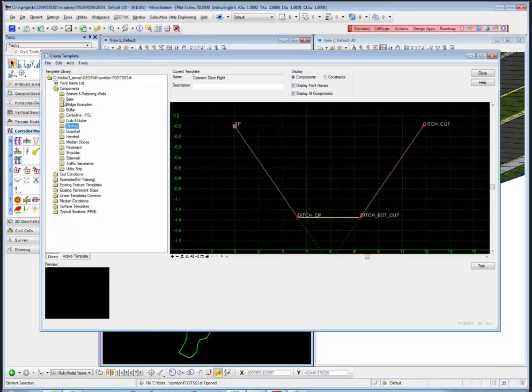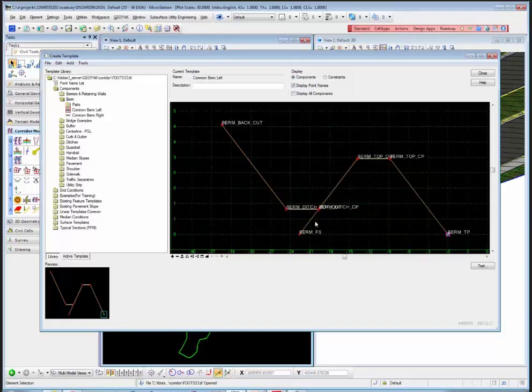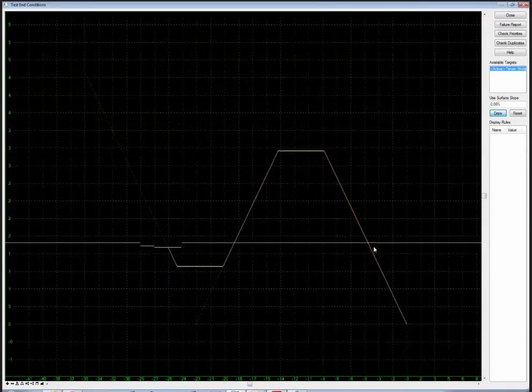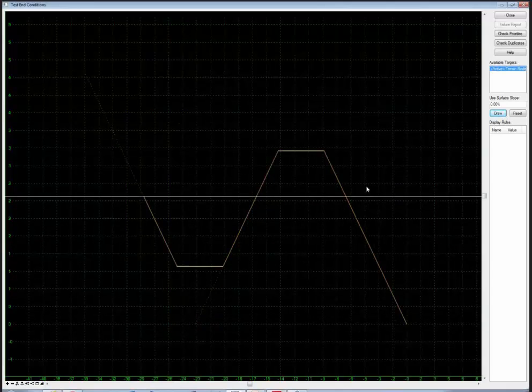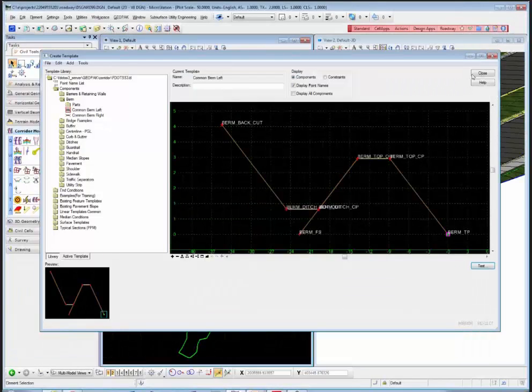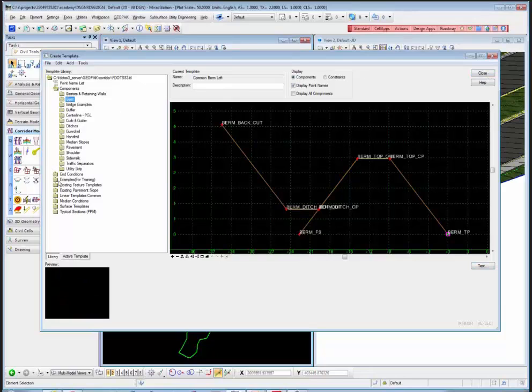And then the same thing with berms. We have basic berms now, where before we had a really complex ditch berm situation. Now we just have this standard situation here where, depending upon where the surface is, you're going to get either a berm with a ditch or just a berm. I'll cover what some of these other dialogs are here in a second. I'm just trying to basically cover the changes. The typical sections, well, let me just keep continuing down the list here.